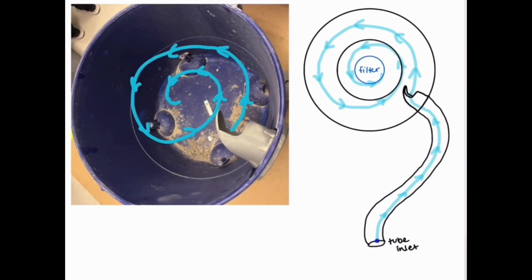More specifically, we can trace the path of fluid flow starting at the suction hose inlet, which sucks air in from the atmosphere, increasing the flow's velocity and thus decreasing the flow's static pressure. This pressure drop is what provides the force that allows the shop vac to suck up the water or debris. From the hose, we can trace the flow's path to the inlet of the collection bucket, which has an even lower pressure than in the suction hose.